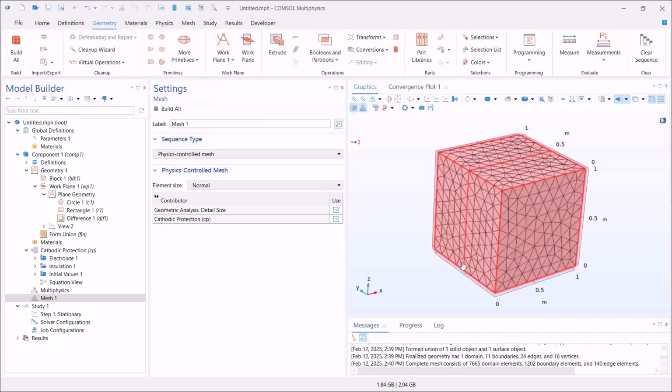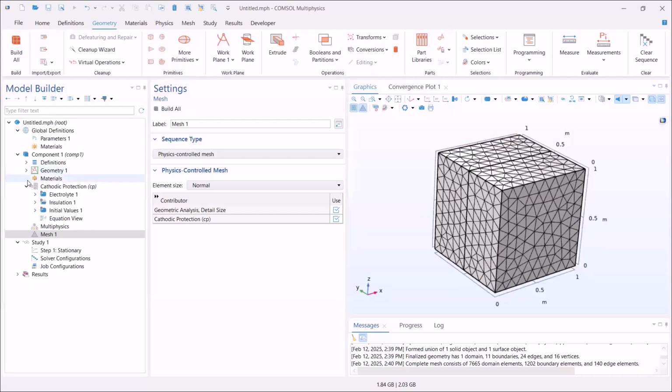And if you were to model, say, that this was a very thin plate, say a 1 millimeter acrylic plate or something like that sitting in the middle of this, then you would have very small elements inside this and on the outside of the thin plate. By using this thin layer functionality, it's easier to save a lot of elements.